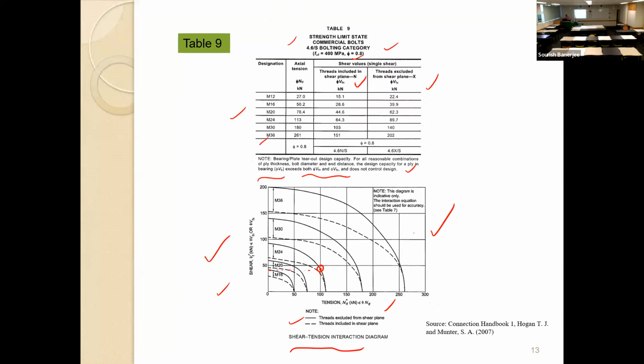And in fact, not only the reinforced concrete column interaction diagram we have looked at, we have also done the steel column. It's not only reinforced concrete columns; even the steel column, when it is subjected to an axial load and then bending moment, we have seen that this kind of interaction diagram is required. That means we have compression and the bending moment.